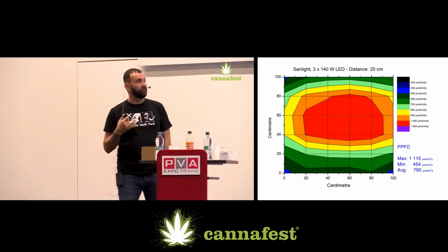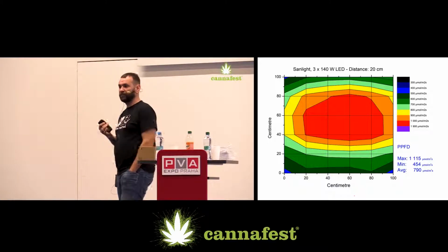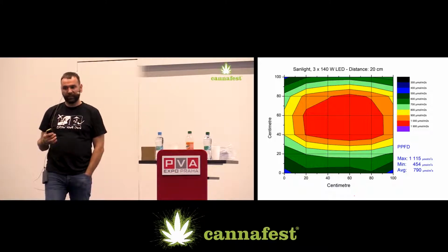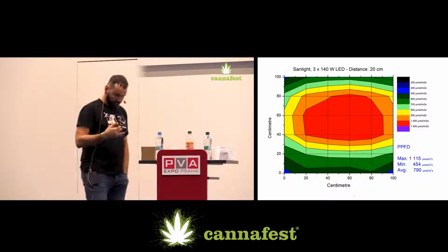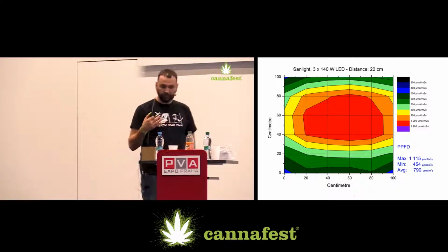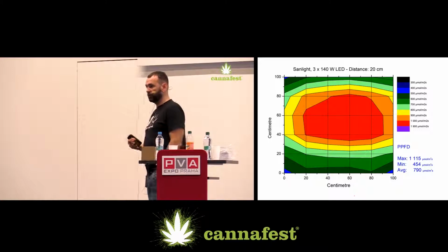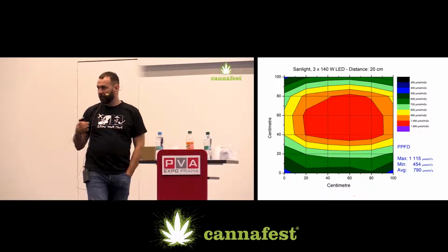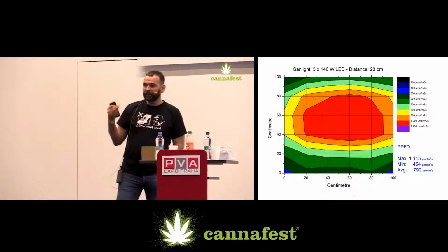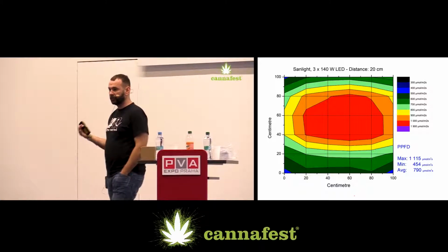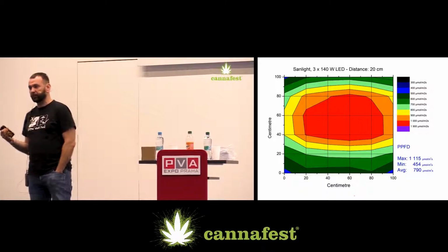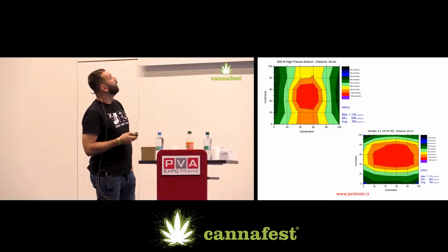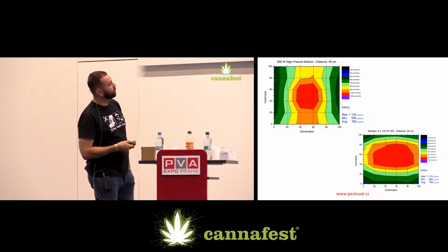Practice has shown that when using high-quality LED modules, we can save something like 30%, but never 50% or more. I trust that this will keep developing and moving ahead, but at the moment, this is what you can reckon with. So if anyone thinks about replacing your 600 watt sodium with a LED module, don't buy this one.